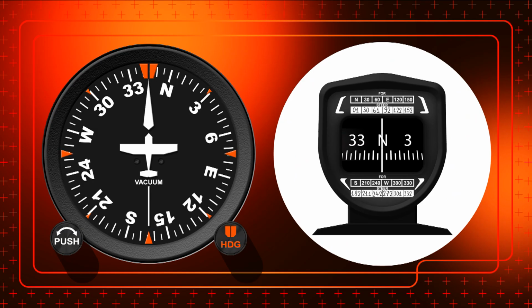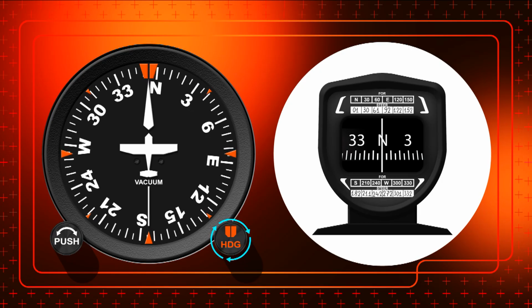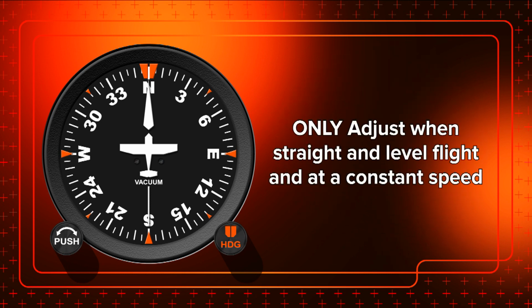magnetic compass, which is situated on the glare shield of a Cessna 172 aircraft, and if required, adjust the heading indicator to match the heading reading on this compass instead, since the magnetic compass doesn't get affected by this type of wander. However, this adjustment should only be made when the aircraft is flying straight and level and at a constant speed, as this will be the only time the magnetic compass will indicate the heading correctly.